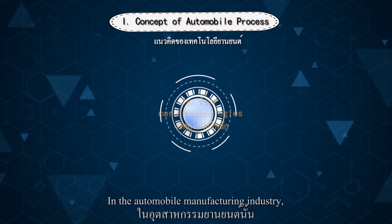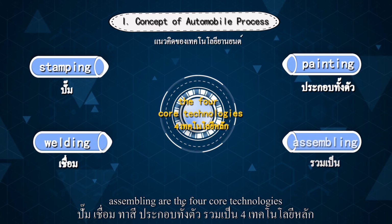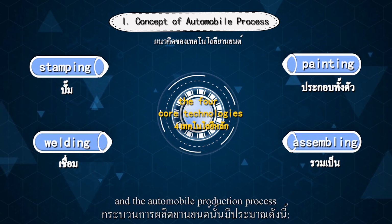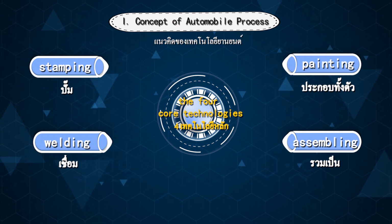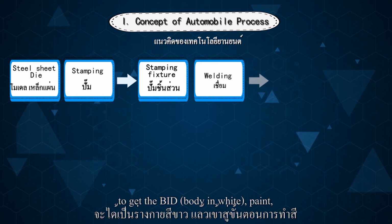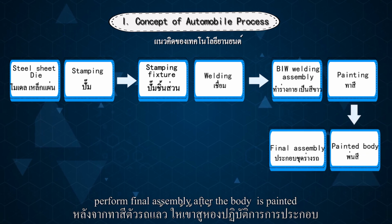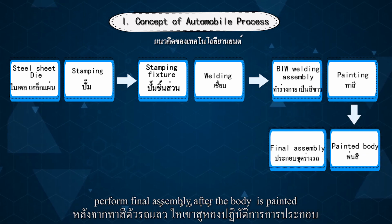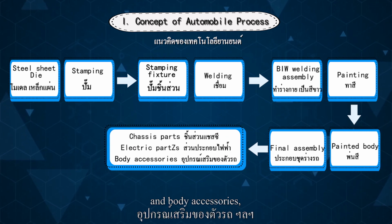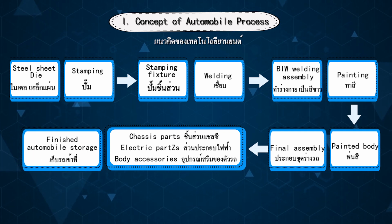In the automobile manufacturing industry, stamping, welding, painting, and assembling are the 4 core technologies. And the automobile production process is mainly as follows. Stamp the steel sheet, then weld the stamped parts to get the BIW, paint, and perform final assembly after the body is painted. Finally, install the chassis parts, electric parts, and body accessories, and store the automobile.